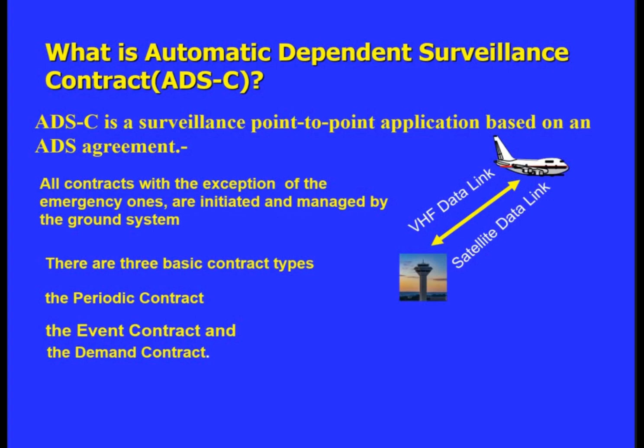The ADS level displayed for the flight data record does not update dynamically. That is to say, unlike a Mode C level readout, that is radar, the ADS level displays the last level information reported and does not change until a new report is received.